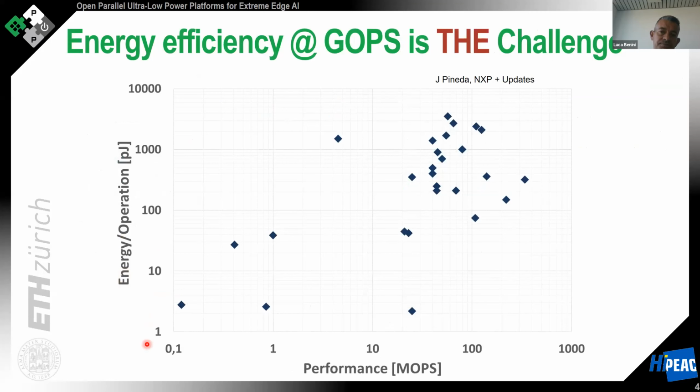So if we look at the challenge of bringing these operations to the edge, or the extreme edge near the sensors, you see that typically near the sensors at the extreme edge, we have limited computational capabilities. And these are usually provided by microcontrollers. So the well-known ARM Cortex-M microcontrollers like M0+, M3, M4, M4F are the microcontrollers that can be deployed at the extreme edge near sensors because they have low cost, and they are very flexible, so they can be adapted to a very large number of computations, not only neural networks, but many other computations.